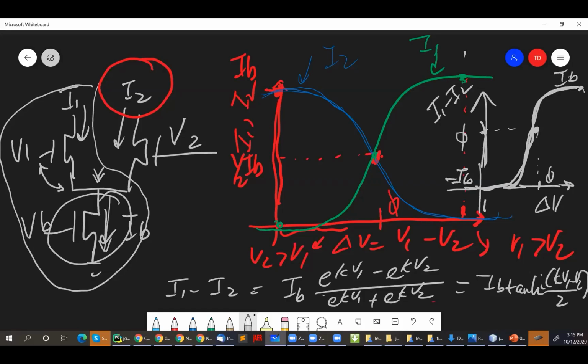Because if this V value moves down for some reason, and one way to move it down is by moving these voltages down, because remember, V has to follow whichever is highest, then you could make this transistor go out of saturation. So it's still operating above threshold, but it's now in the linear regime.